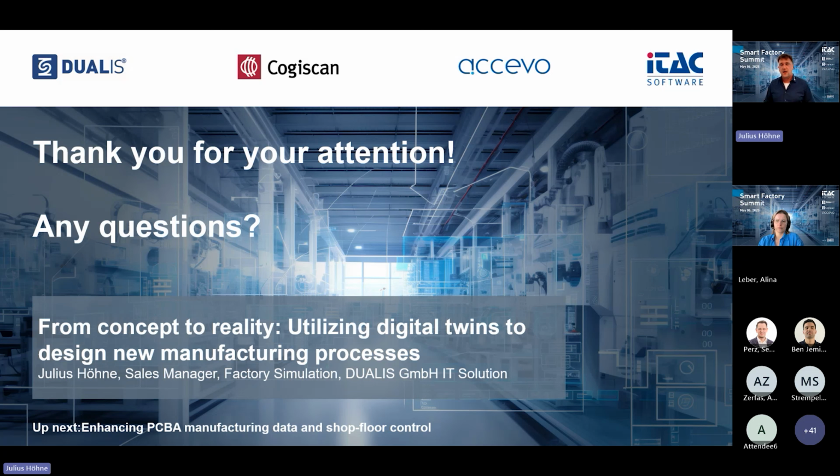Yes, depending on what you want to do exactly. If you have a firmware of a CNC machine, in that moment, we cannot simulate that so deeply. But if you want to update an existing SPS program, a PLC program, or you want to improve the program of a robot, that is exactly what we're doing with simulations. After you set up the machine and commissioned it, the process is not finished. You come to the point that you say, okay, we can improve it a little bit, and the improvements can be tested in the simulation. So that is a possibility to validate software updates.